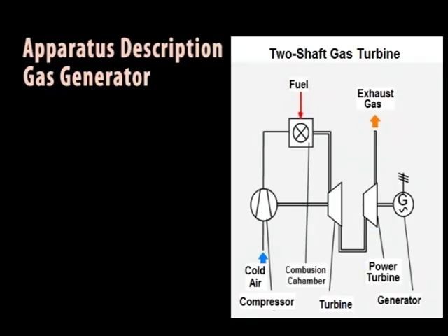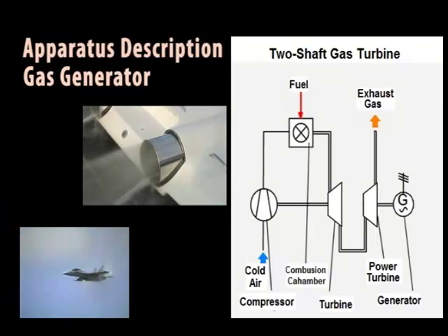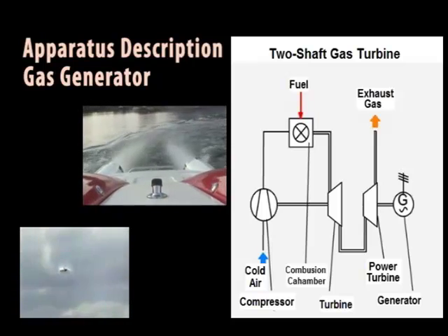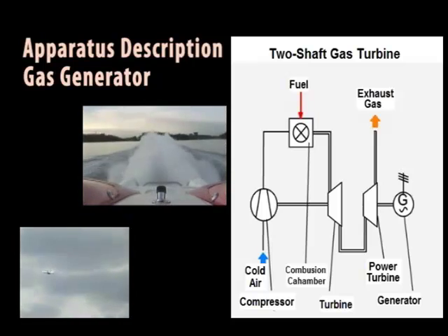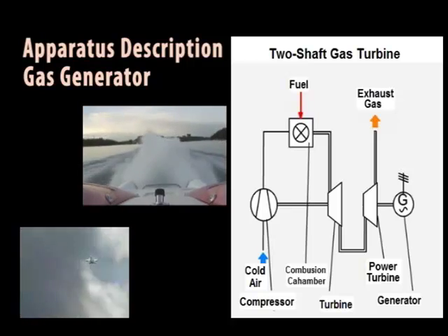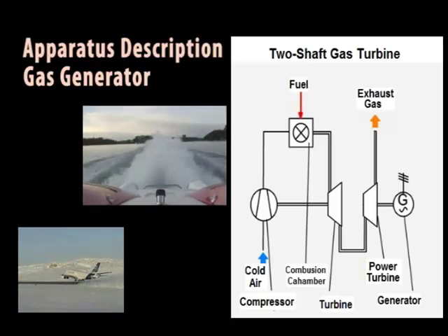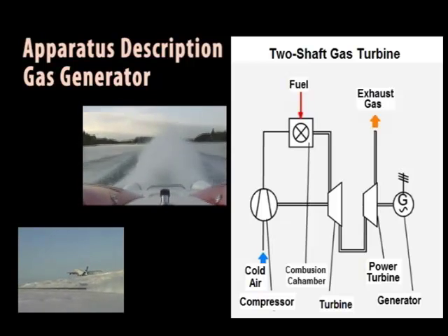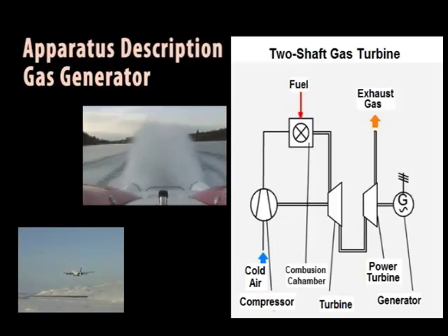The advantage of this arrangement is that a change in the load or the speed of the power turbine has little or no effect on the compressor. This continues to run at the optimal speed in the best efficiency region. Even the jamming of the power turbine cannot cause damage to the plant. For this reason, the two-shaft plant is preferred for vehicle and ship drives with widely varying load requirements. In addition, the speed of the drive can be better matched.